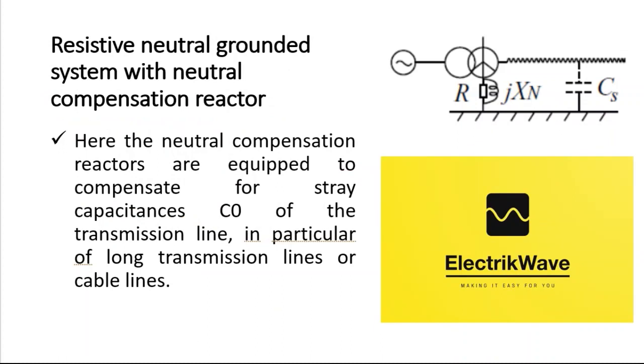Resistive neutral grounded system with neutral compensation reactor. Here the neutral compensation reactors are equipped to compensate for stray capacitances of the transmission line, in particular of long transmission lines or cable lines.